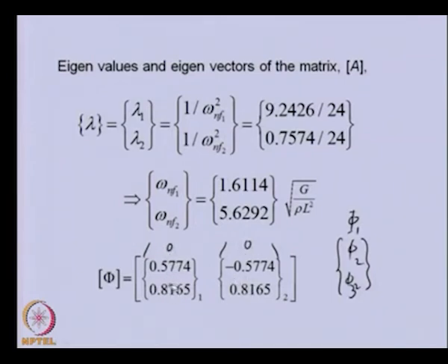This will be clearer if we take more number of elements. The size of the eigenvector will be larger, and we can see the mode shape more clearly. Similarly, when we take more number of elements, we will get more natural frequencies, and we expect the lowest or lower ones to be better as compared to the higher ones.